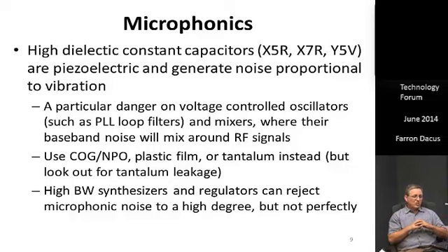And so you have to be real careful in the usage of those kinds of capacitors, and in particular in frequency synthesizers. You tend to hang quite a bit of capacitance a lot of times on, say, voltage controlled oscillator power inputs, because there's noise on those supplies that will tend to degrade the VCO, and a natural tendency is to put a little RC filtering right on that VCO supply line.